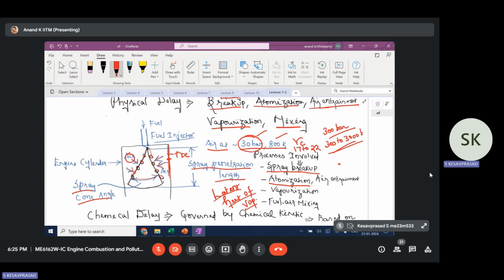So what I said here is I want the drop to be as fine or as small as possible. What is the advantage in forming a smaller drop compared to a larger drop from the perspective of absorption of latent heat? Lesser amount of heat required? No, this is finite. Heat transfer will be faster, sir.